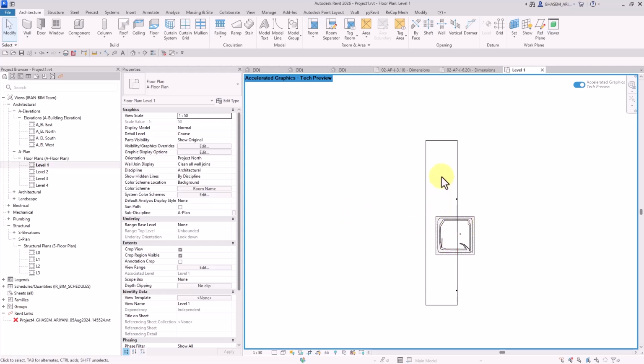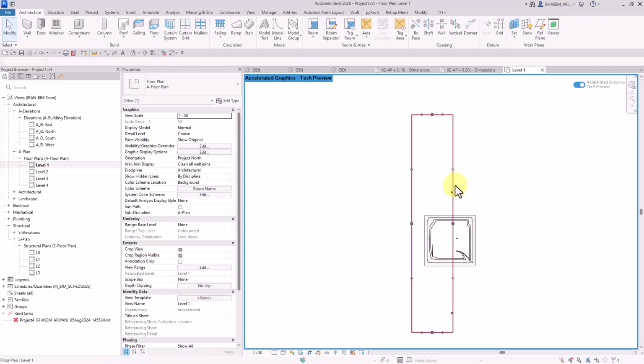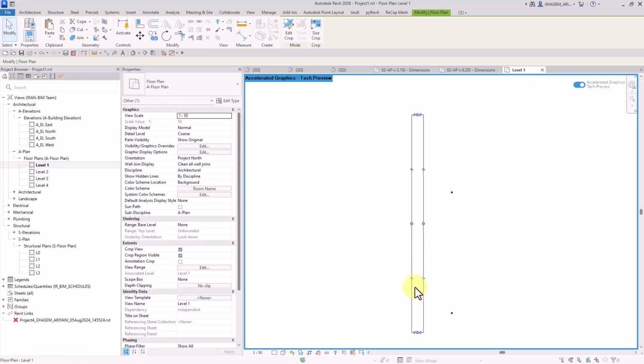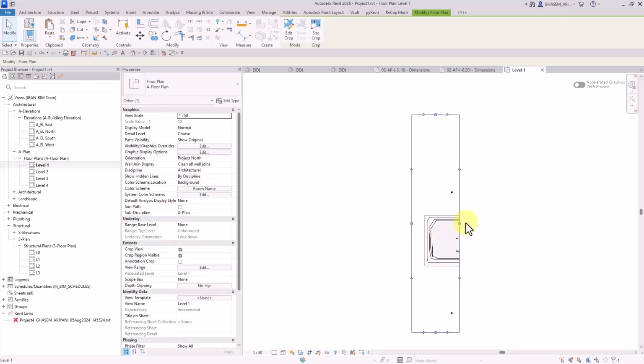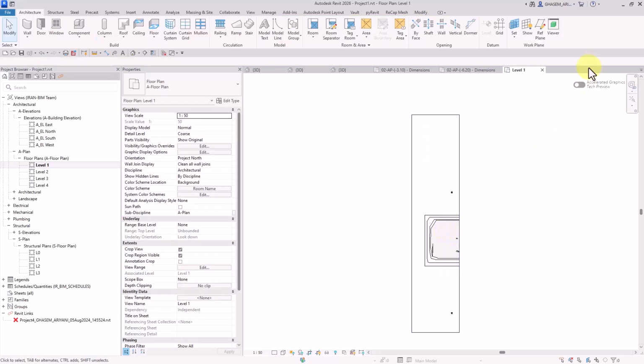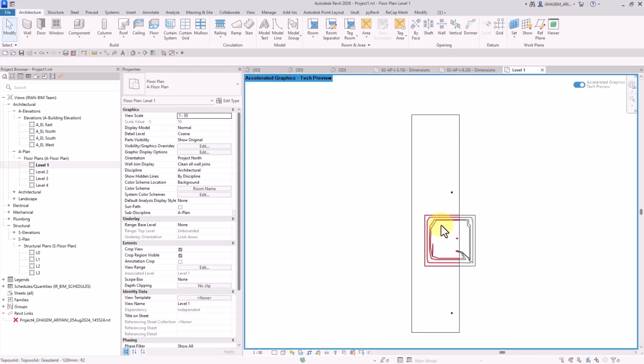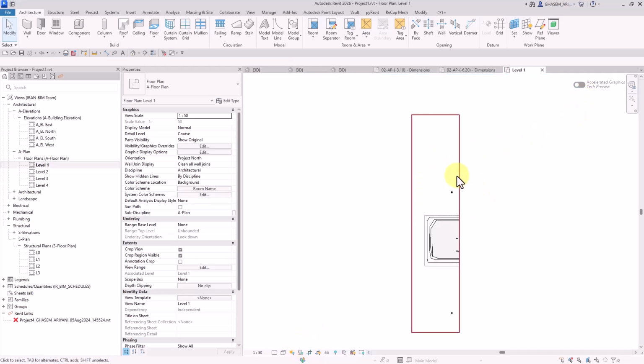As you can see, crop view won't be applied here correctly. To make it right, we should set this outside the boundary. Otherwise, even 1 millimeter would create a dysfunction. Now, obviously, if we deactivate the item, it'll start to work correctly. But if we try using it again, as you can see, once again, the crop view won't be a factor. All right, let me turn this off and set this back again.